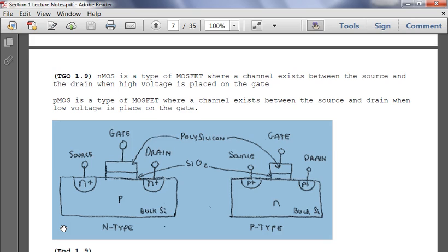And we're going to be learning about something called threshold voltage, which is the minimum voltage required to be placed on the gate in order to create this channel. When you play with HSPICE, you can actually determine that exact voltage by seeing the simulation. Once you hit that threshold voltage, you'll actually get a spike on the output based on what you want. Before, it would just be transient. So you can actually perform experiments using something called Monte Carlo simulation to find out that exact value. Does anybody have any questions on that?